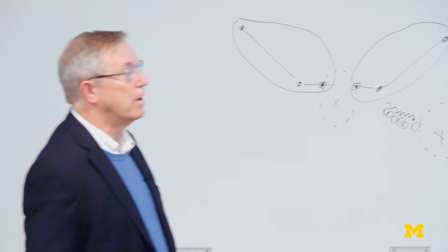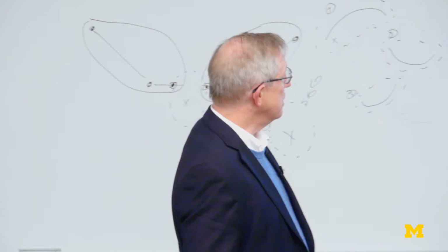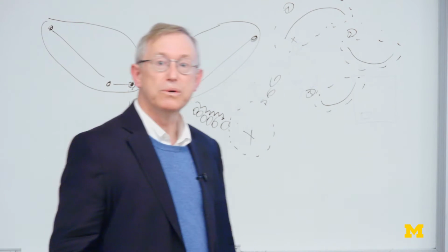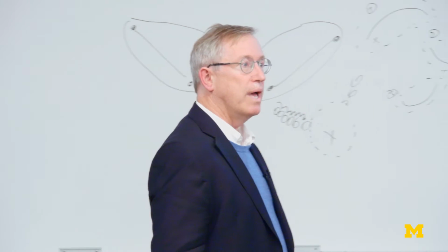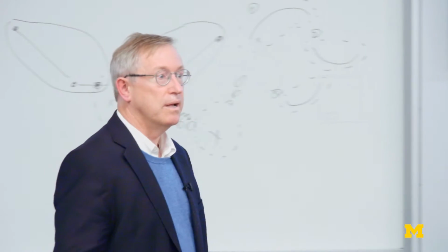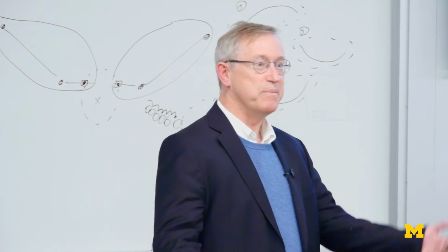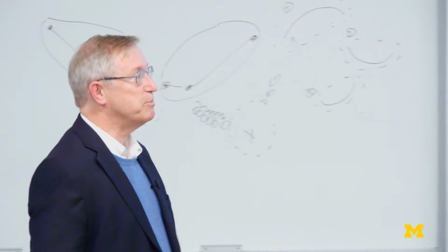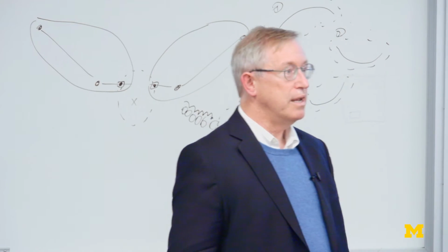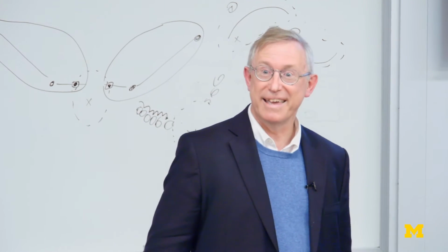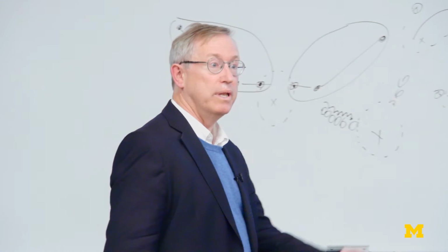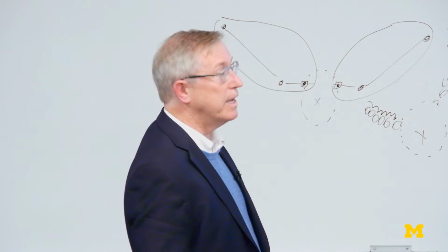Okay, so all these things are amazing technologies, but they're all relatively mature now. We haven't seen a huge advance in laser sources or in modulator technology and so on for a while, a decade or so. And so now it's time for information theorists to come in and squeeze the last few bits per second per hertz or whatever out of this type of channel. Okay? So finally, optical communication engineers have decided that just turning things on and off quickly just doesn't cut it anymore. And we need more sophisticated coding and modulation ideas.